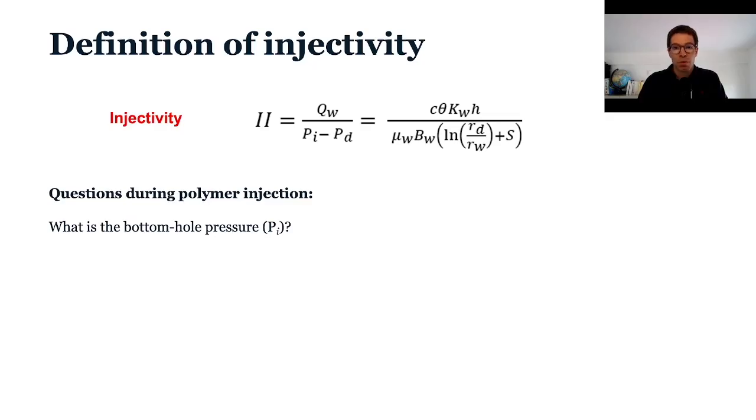But this is important. And we could say, well, it's low concentrations, so it works. But it does work too at higher concentration. And I'll show you examples. When you have 10, 15 centipoise, the pressure drop in the pipe with polymer solution can be up to 70% lower than the pressure drop with water. And this will mathematically impact the injectivity because it will condition the pressure that you will have just before entering the reservoir.